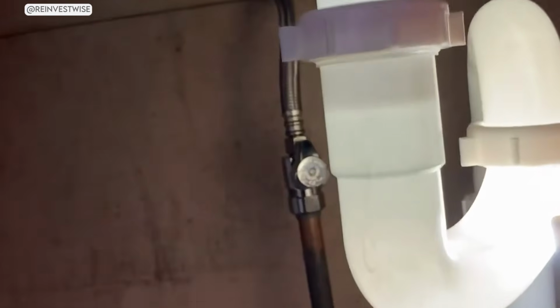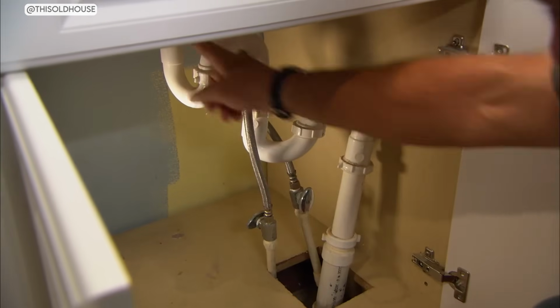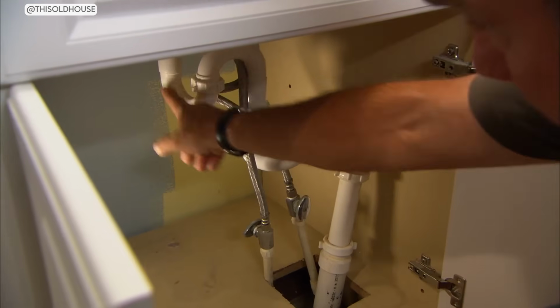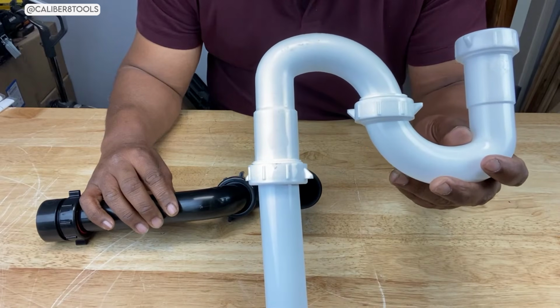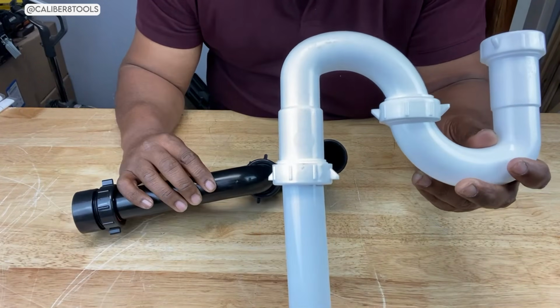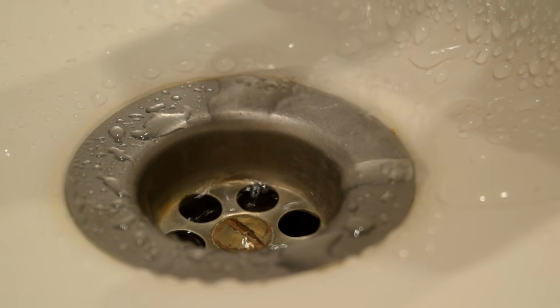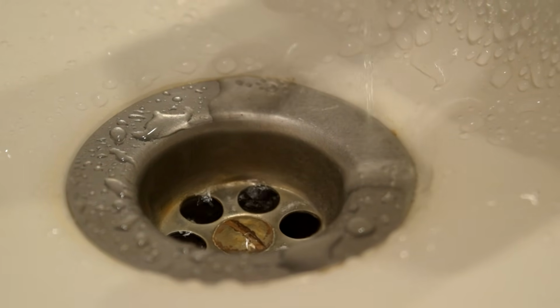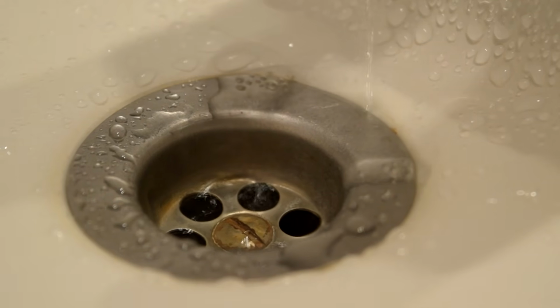And now for the bonus tip that professional plumbers swear by. If you have confirmed that you have an S-trap but you cannot replace it right away, here is something you can do in the meantime to reduce the risk. After every time you use that sink, let a slow trickle of water run for about 5 to 10 seconds after you finish.